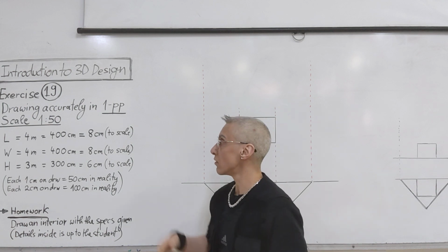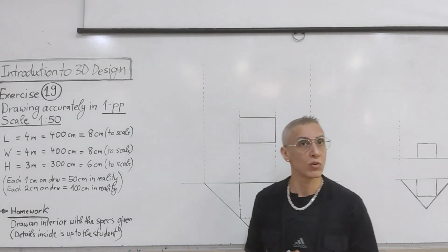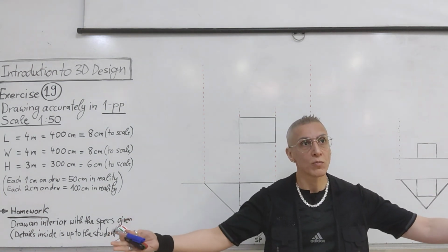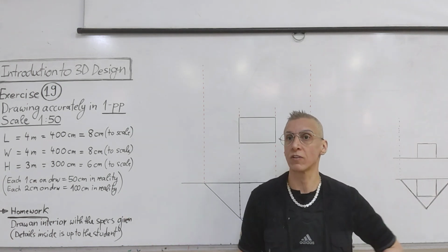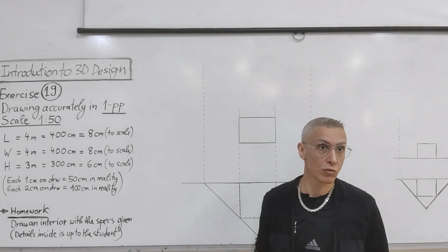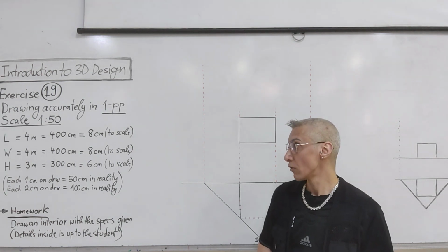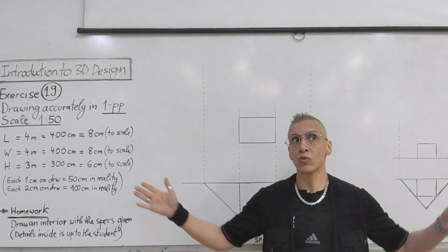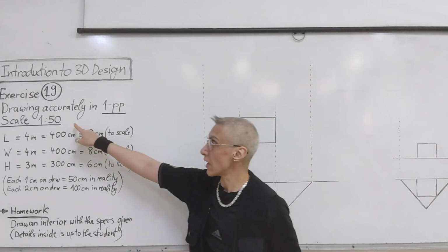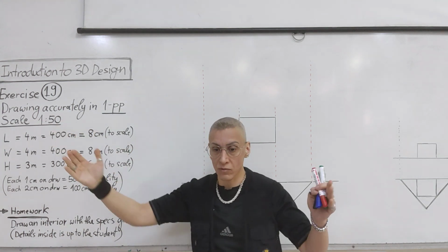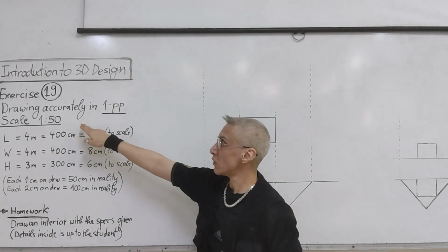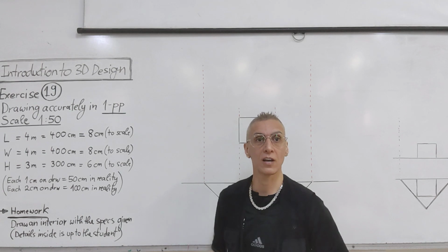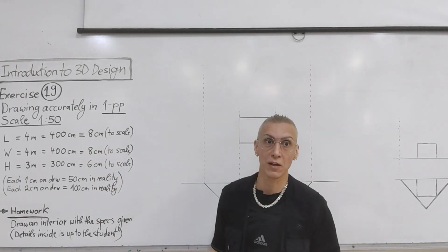Now, first of all, this method in general is mostly used by interior designers when they draw rooms or some open space to show what is inside. So this is what it's used mostly for, this method especially. So we will draw a room, an opened room. Now, as you know, rooms are big, so we need to use a high scale, so that we scale it down to our paper. So we will use a 1 to 50 scale. The real measurements of a room, for example, we will make them smaller 50 times, okay?